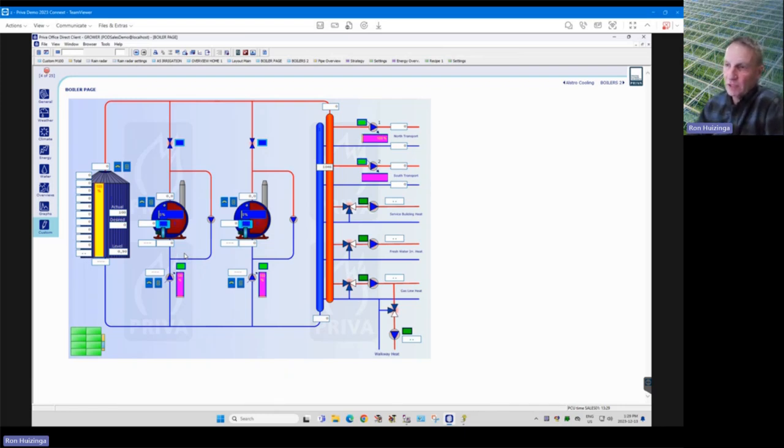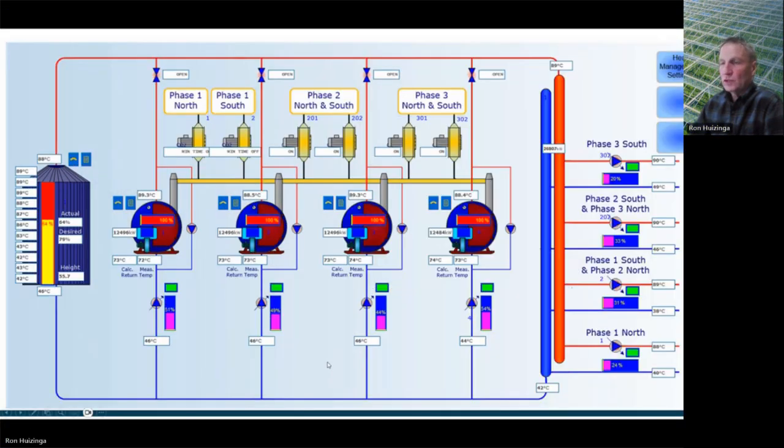Also there are different designs here, because what I'm showing here has no mixing valve, but sometimes there's a mixing valve in here. So there's actually a three-way mixing valve that's also dividing up the water. Then there's only one pump and a mixing valve. And let me see if that other drawing had that. Oh, this drawing's the same.